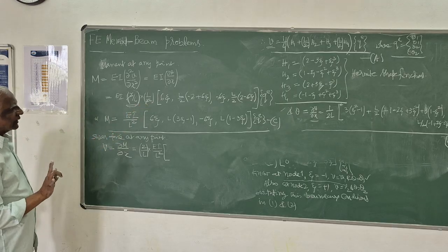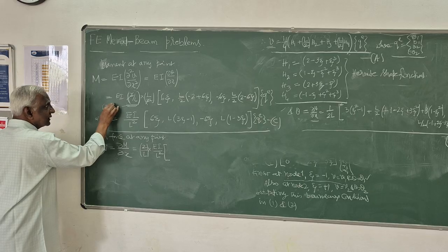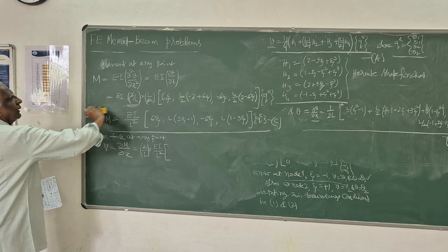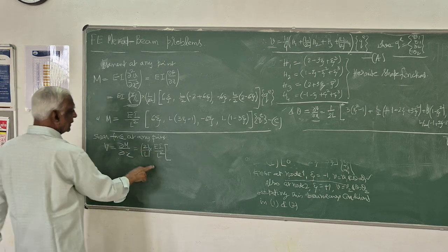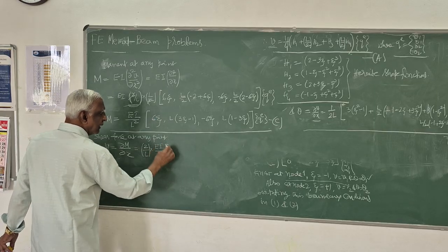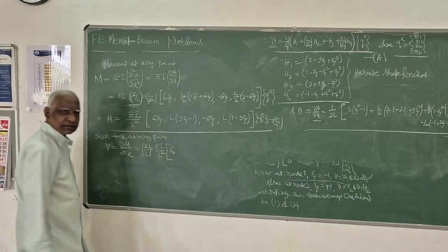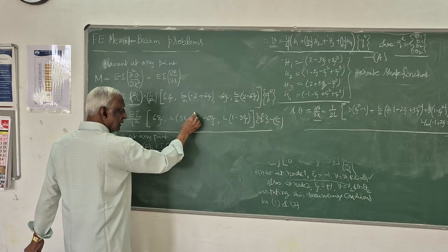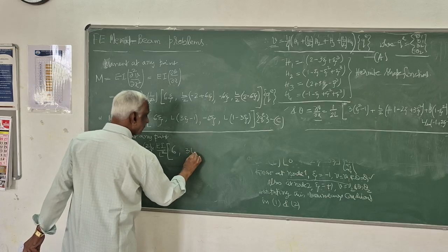So you have to be careful. You have to multiply by that Jacobian inverse. This you have to remember, because we are treating all these elements as isoparametric elements. So here, by L square, here partially differentiating with respect to Z now. It is 6. Here partially differentiating, so this will not be there, only it will be 3L.